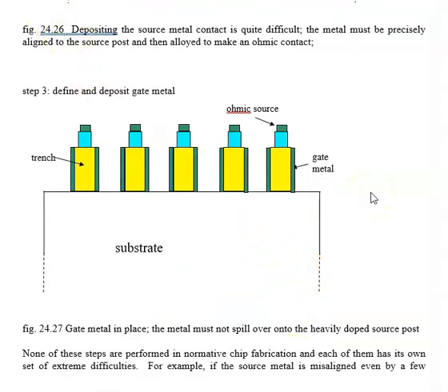And the other thing that one can see, it's maybe a little subtle, but boy, is it a big deal: the incredible difficulty in fabrication. We have to align the ohmic source metal to the source, and there can be no overlap whatsoever. If there's even a little spill of this metal onto this region here, which is called the shoulder, the whole thing will become shorted.